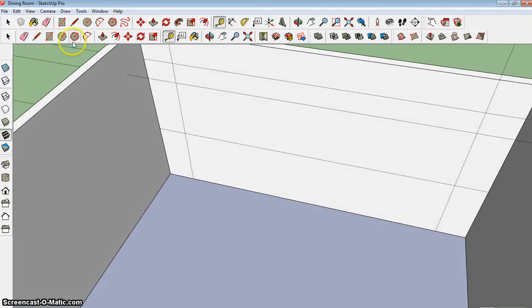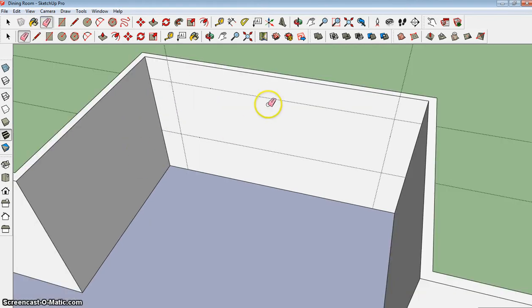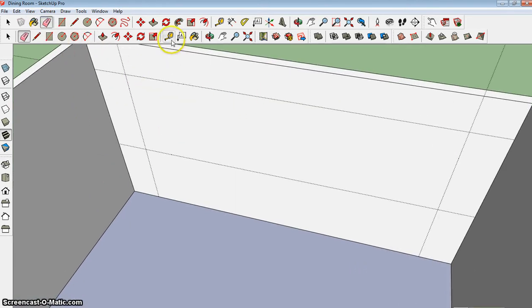Here's another telltale sign of that. If I try to draw a rectangle right here, notice that there's no intersection popping up, whereas here it's finding where those 2 lines cross over each other. That's because these don't cross each other, as you just saw. So we're going to go ahead and erase this line and redraw in that other tape measure line that I just put in there. So we're going to bring this down on the blue axis. I'm going to go 8, enter.